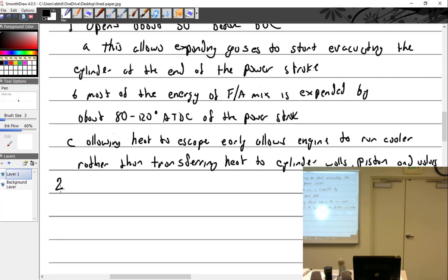All right, so the thing is, though, you can't cool a valve sitting on its seat if the seat is overheated. You got to have a cool seat. In order to have a cool seat, you got to get rid of the escaping gases. You got to let the gases go that are just heating up the cylinder. So that's why you want the cylinder head temp to be low.